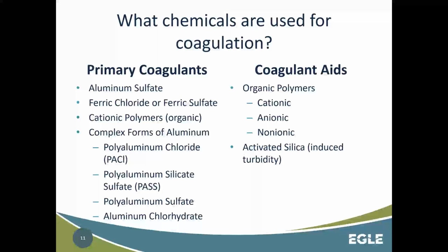Other plants will look at it from a time standpoint, and say, we know that a backwash is going to be required after, let's just pick a number, 20 hours online. So we're just going to backwash the filters after 15, because we don't want to get close to when it's actually needed. And other plants will look at the rate of water production, and when a filter reaches a certain production level, they'll decide to backwash the filter in order to increase their production.